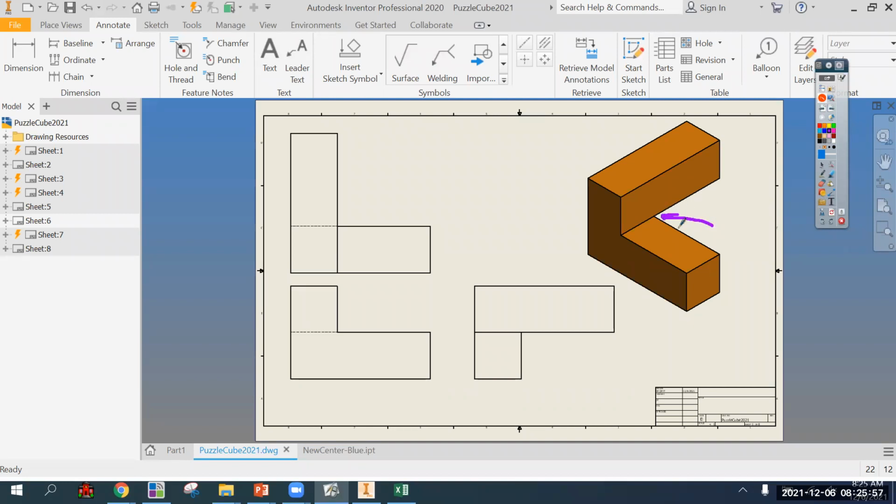There's an edge back here. That's what this represents. There's no edge on the front face, but the edge where this face turns into that face is hidden, but there is an edge there. And so you would draw, if you were actually hand drawing everything, a dashed hidden line. The computer takes care of it for you.